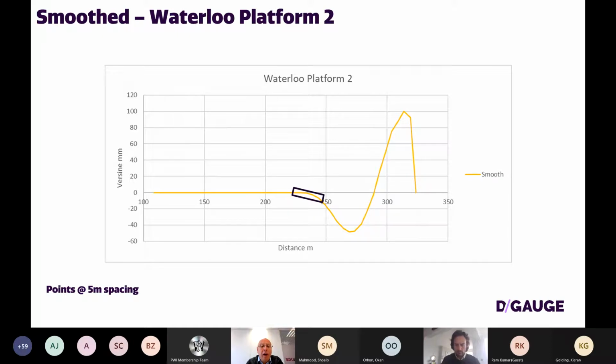It's a very much amplified scale, but we can see now an order of magnitude by order of magnitude how that vehicle is going to behave as it goes around the curve. We can see the effect of that transition curve in terms of how the vehicle will relate to the track underneath and in relation to any objects around it, such as the platform in this particular case that we're trying to calculate the overthrows for.